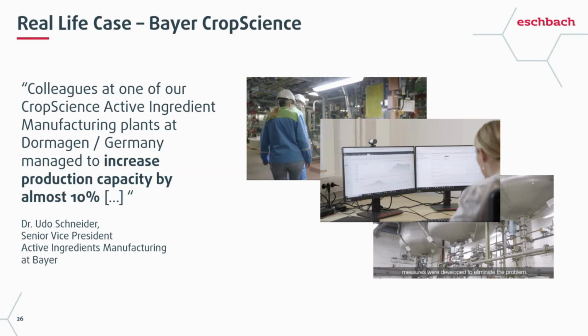And once they identified it, the solution was really simple. Preheat the reactor for this step. Make sure that it is at the right temperature when the product gets in, to avoid this viscous layer on the outside of the reactor. Yeah, a massive one-off improvement with a really simple step. And it involved having the data that they needed, having the context of the losses: okay, the loss is it's too slow. The context is it's because we have this high viscosity, and we have the high viscosity because it's too cold. And then reviewing the data and working as a team to implement the improvements.